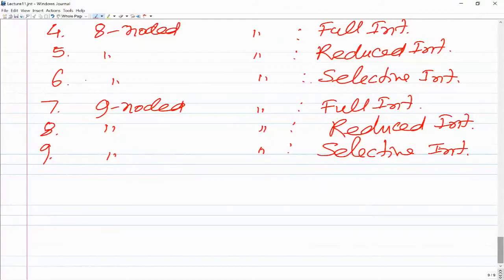Because stiffness is under predicted, we add an additional stiffness term or damping term. The stiffness term is for static problems and problems with low strain rate deformation.